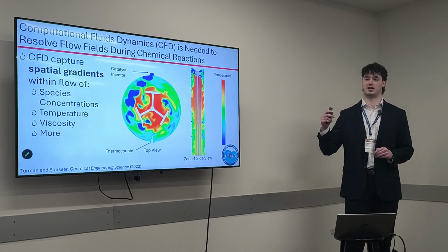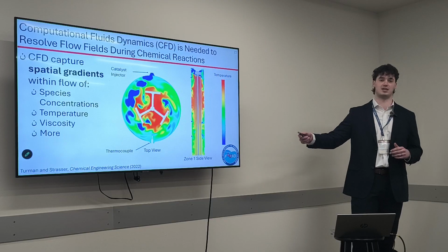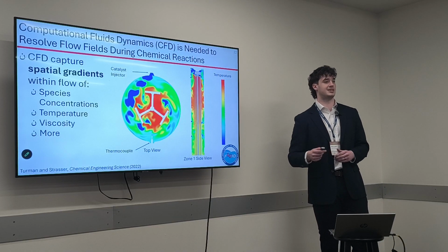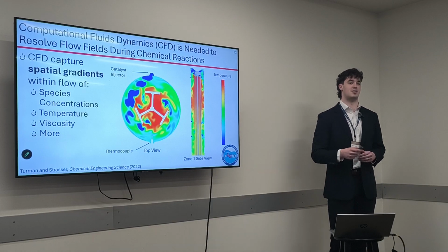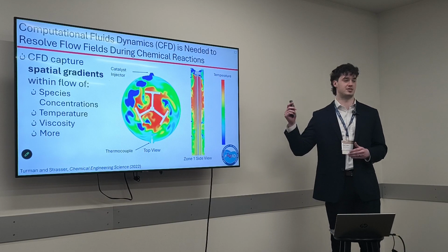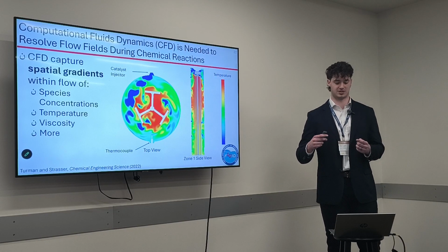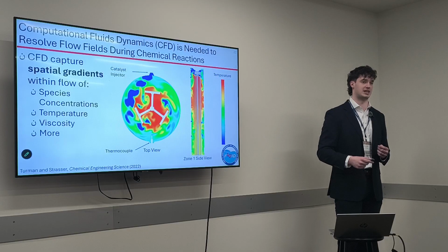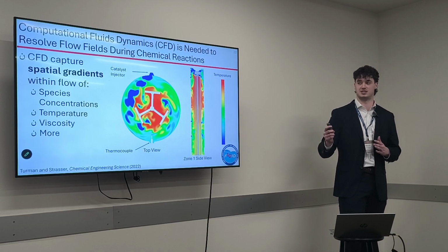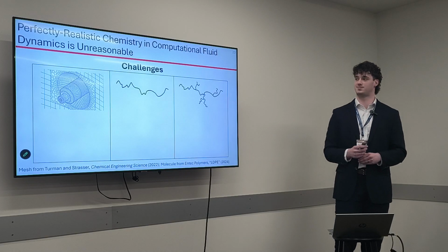And if you're using a CFD CSTR or a normal CSTR, you're not getting all this refinement and you're losing insight into localized phenomena and potential reactor suboptimal performance, because all these gradients can affect the reactor efficiencies or rates. So CFD is needed if you want to look into the mixing or any of these gradients.